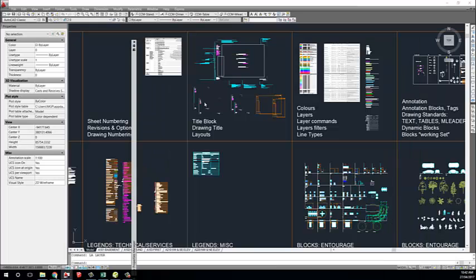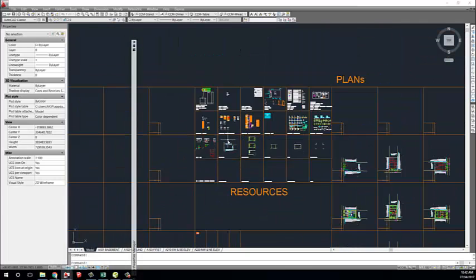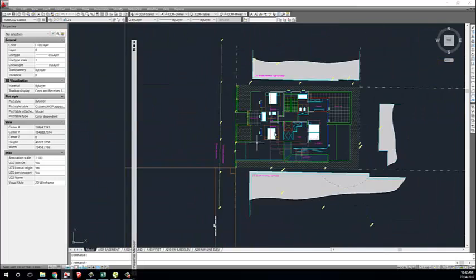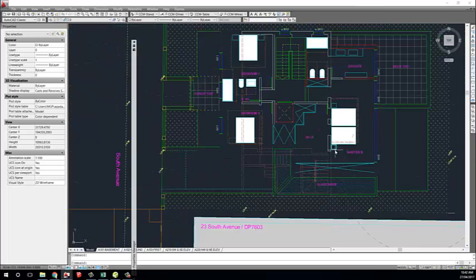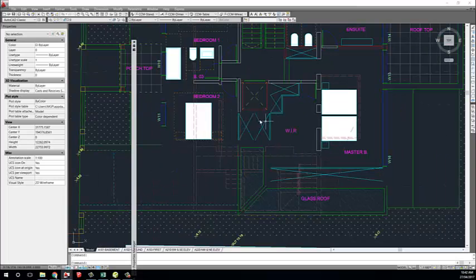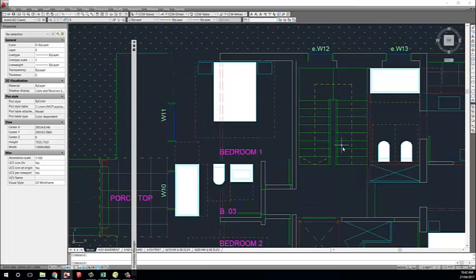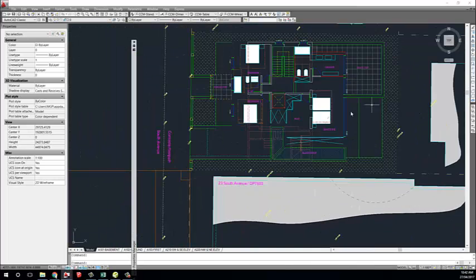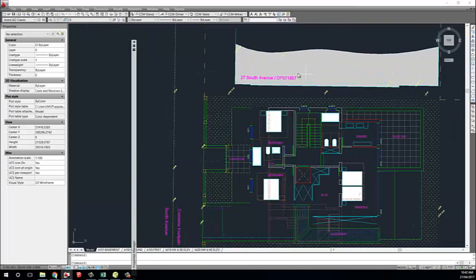These are not really related to the project itself as physical things, as something that you can touch, but give information. That's very simple. Like these rooms will be in the layer annotation. These wardrobes and furniture will be in layer entourage. These symbols here will be in layer diagrams. Anything that is a diagram. And then in the internal reference, you can use layers, or you can use just by color.